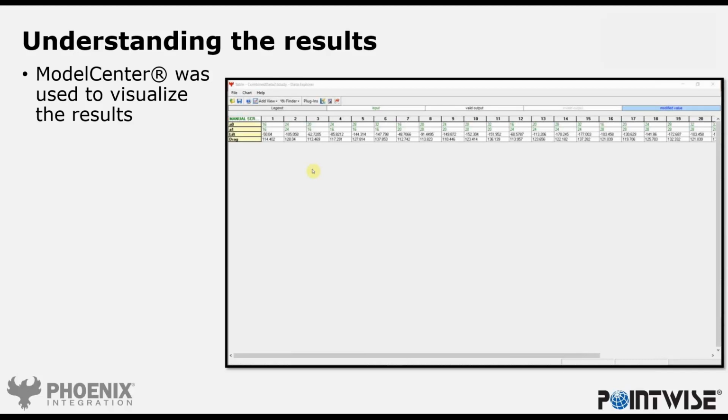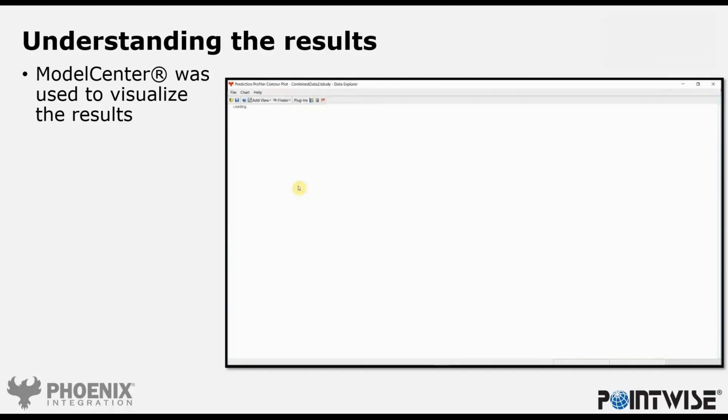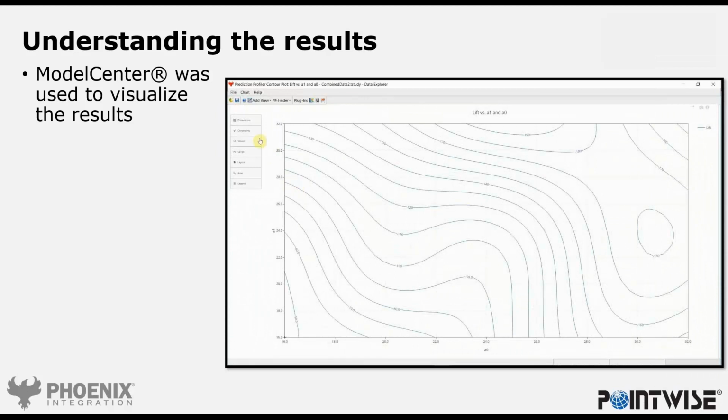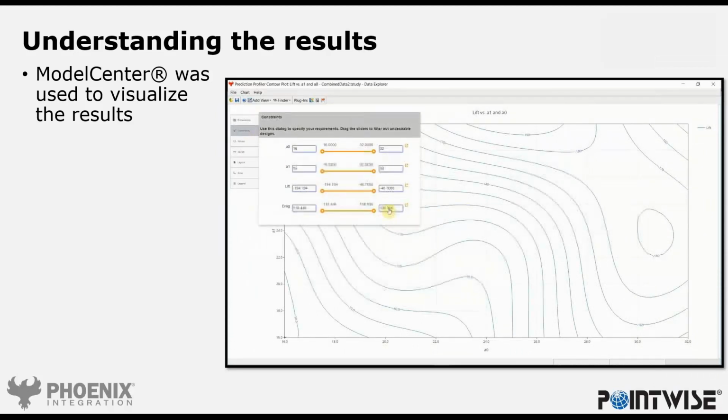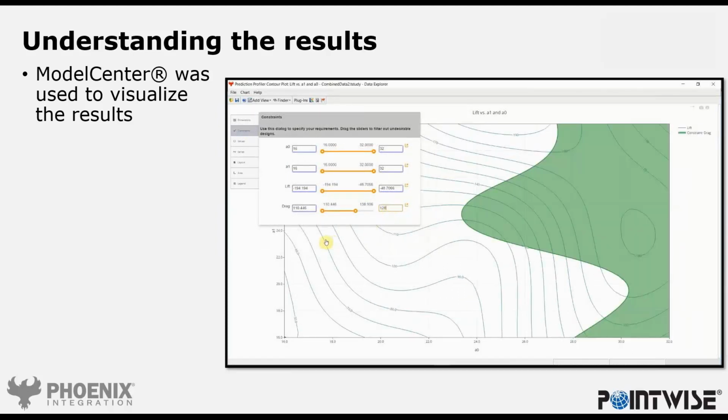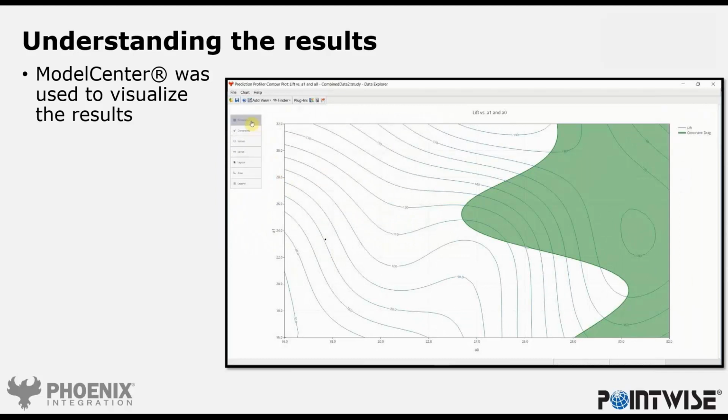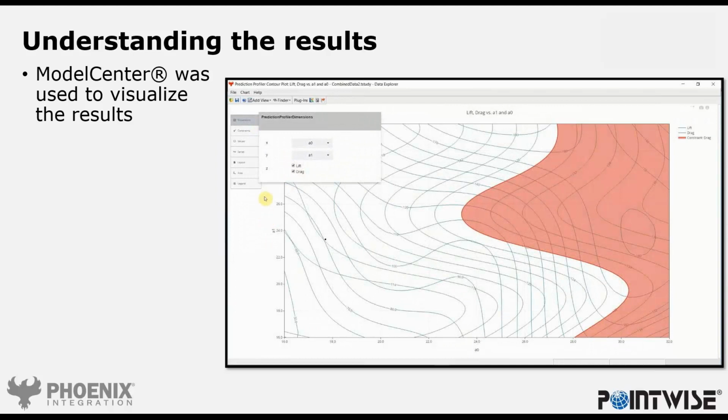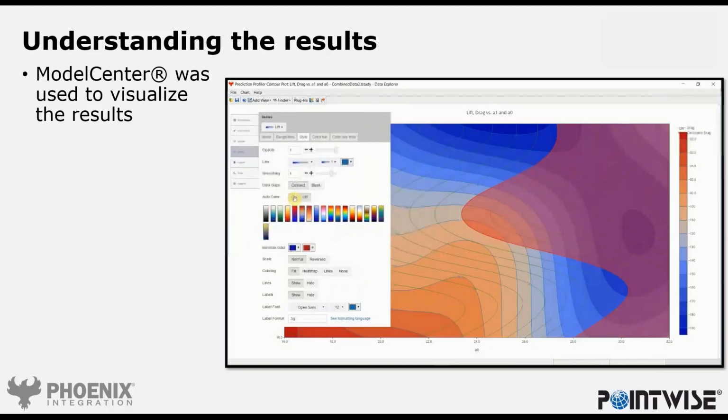And in this case, I can use contour plots to visualize and understand the design space. Here I'll show the video of setting that up. It's actually just real time because I wanted to show you how easy it is to set up this kind of analysis. So here we have a contour plot. On the lower part, we have our root angle of attack. On the y-axis, we have our tip angle of attack, A1. And so the upper left region of the screen represents an angle of attack that's higher at the tip than the root.